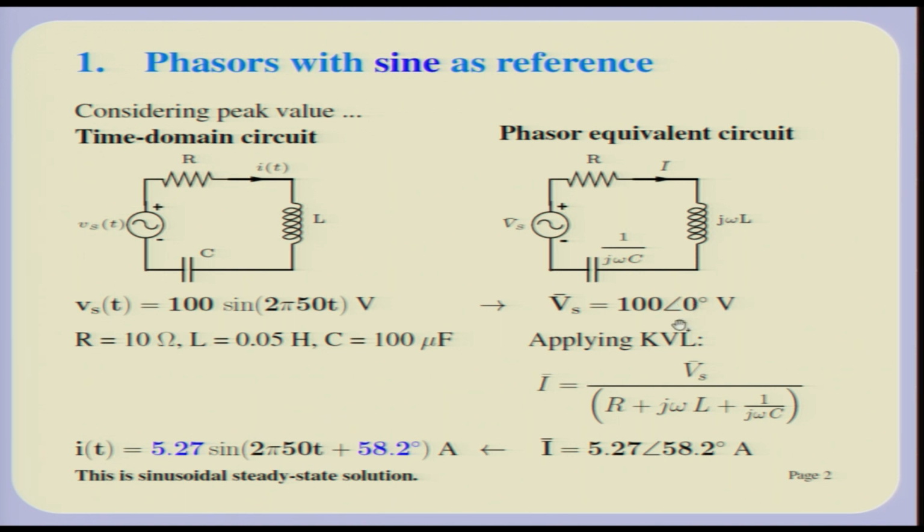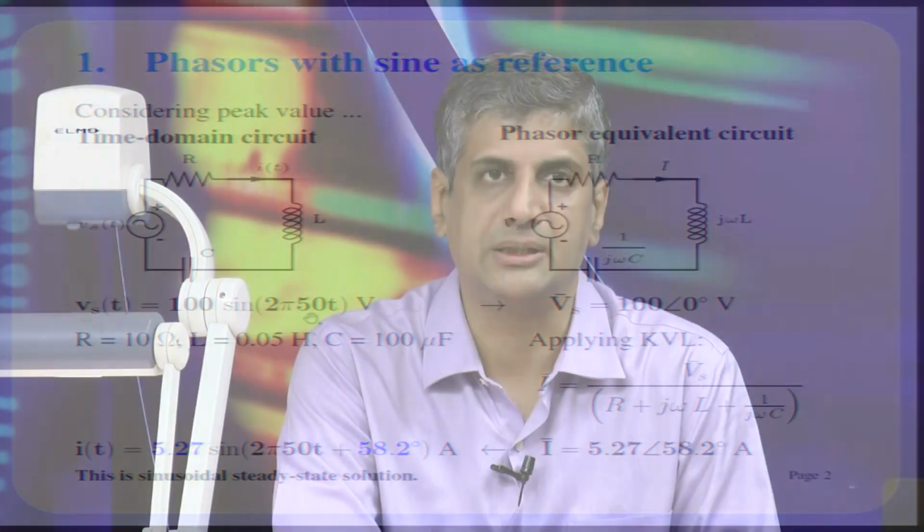Okay. So, what does it mean? This has got a magnitude of 100 and the phase angle, if you assume sin omega t is a reference, then the source has a phase shift of angle 0. So, what this means, this is effectively a phasor. It is implicit that it is varying at 50 hertz. Although the frequency is not given, it is implicit that there is a normal frequency you are referring to.